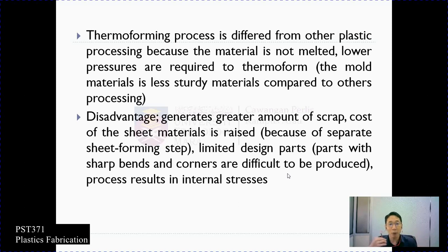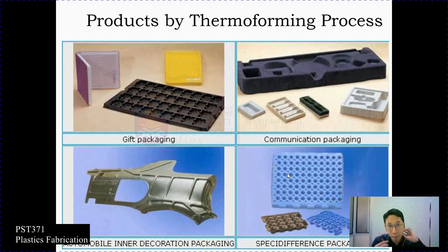Okay, and then the process results in internal stress. Of course, thermoforming is related with high stress of the material. Okay, as compared to other types of technique, although they also have stress of the polymeric material, however, thermoforming has a greater internal stress. Okay, this is some of the illustrations of the product using a thermoforming technique.